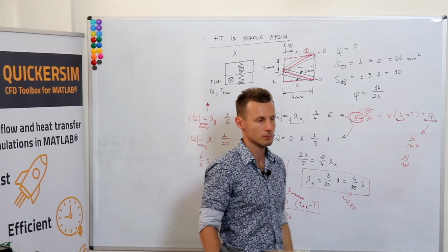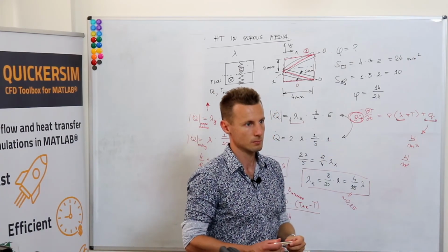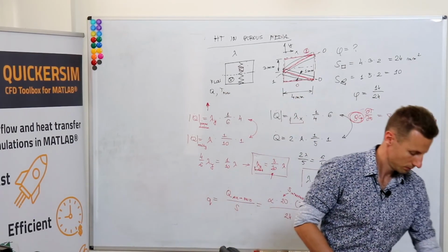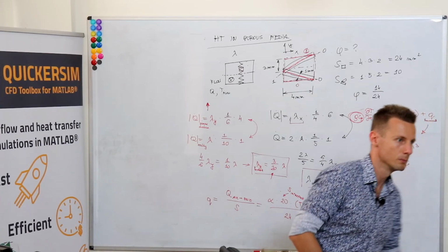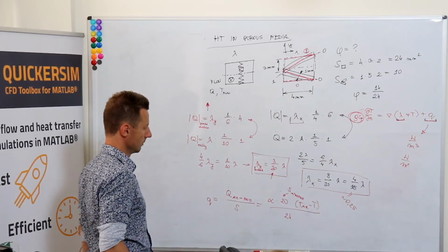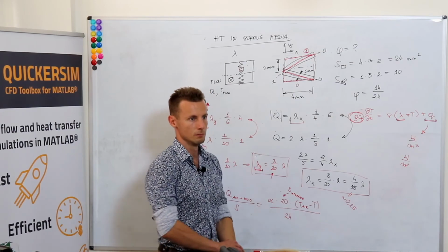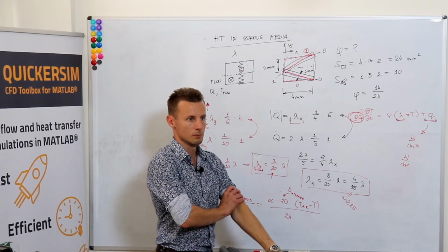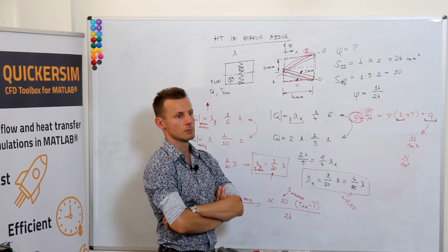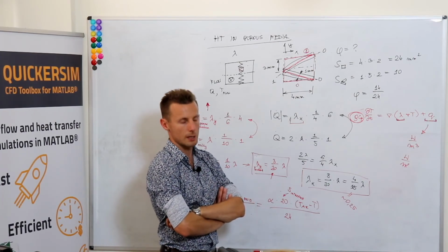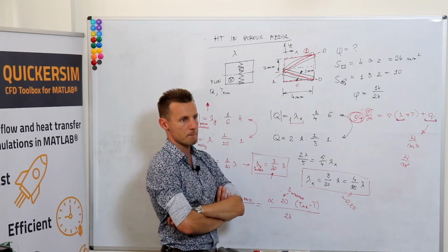Maybe one comment based on a very similar project that we did in December. The temperature in the source at the bottom is set as constant, and that's absolutely fine, providing that we make the assumption that the airflow is sufficient for the temperature to not drop or increase over the time of traveling through, or that this increase is negligible.